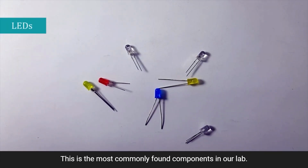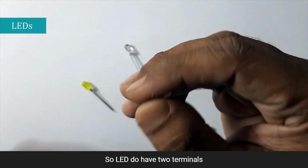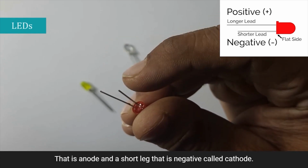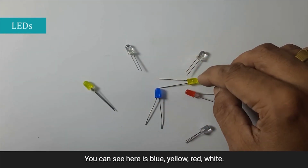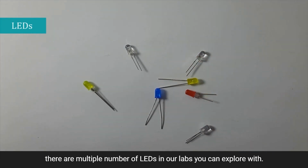These are the most commonly found components in our lab. This is called an LED. The LED has 2 terminals. The longer leg is called positive, that is the anode, and the shorter leg is negative, called the cathode. It comes in many different colors. You can see here it's blue, yellow, red, white. There are multiple LEDs in our lab that you can explore with.